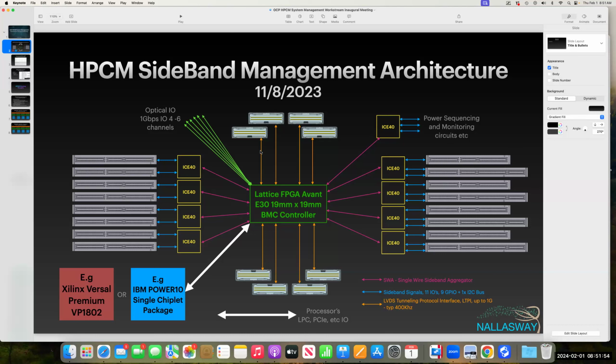And then we've got these topology interconnects. So we've got 8 of these. These are the ones that connect all the modules together, so they're module to module. Instead of putting a bunch of sidebands on here, we want this to be a universal interconnect. So you could put Ethernet over here, or you could put PCIe, CXL, or NVLink from NVIDIA or Infinity Fabric from AMD, etc. So it could be any protocol, any speed.